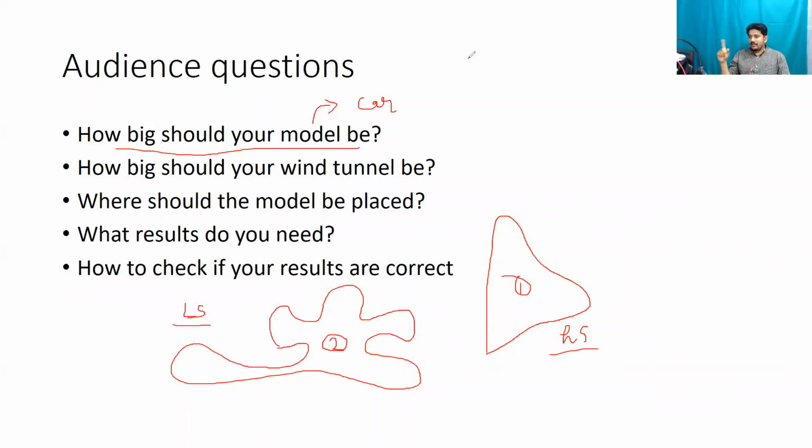Now remember, for a higher velocity, the mesh requirements would also get finer. So even though you scale down, you need to have smaller meshes so that you're resolving the turbulence. Because at the end of the day, remember, to get the aerodynamic performance correct, you need to simulate your turbulence correctly. If you're not simulating the turbulence correctly, then that's it. Your simulation results are wrong. That's it. There's no argument. So how big should your model be? What is the answer to that? It doesn't matter. So let's just pick 1:1. Just make sure that you're modeling things as realistic as you can.